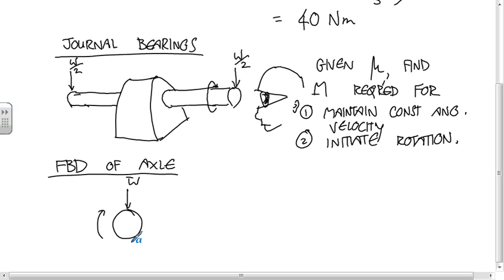And so even though every point is touching, if you represent the total force applied by the bearing as an equipollent system where you only have one total force acting, that can move around depending on what the motion is because the distributed load changes.